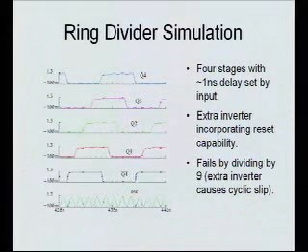Okay, so just a simulation to show how this works. This was the first look at the first flip-flop. This is the original signal coming in. 1 full cycle later, it gets transferred to the second one, to the third one, to the fourth one, gets inverted, and then continues to propagate through the chain. So it's just the single lower frequency signal running around the circle.